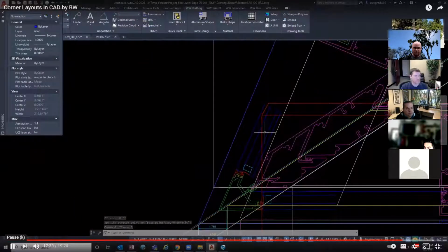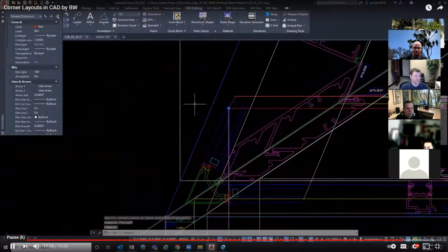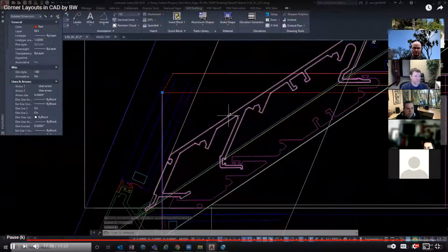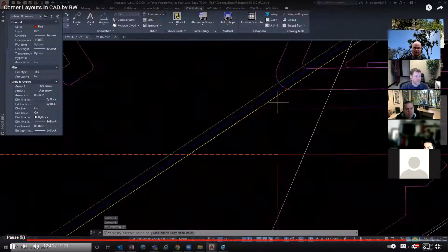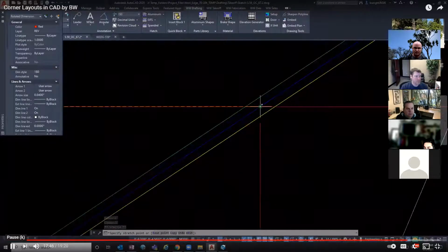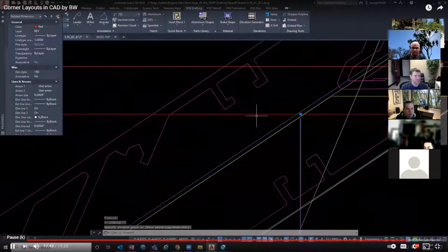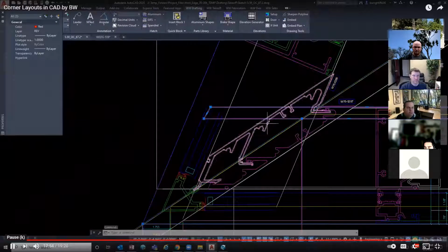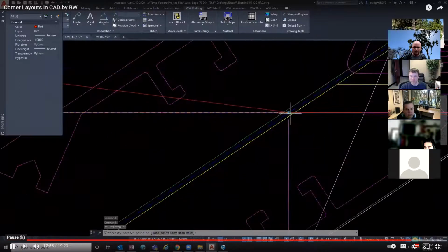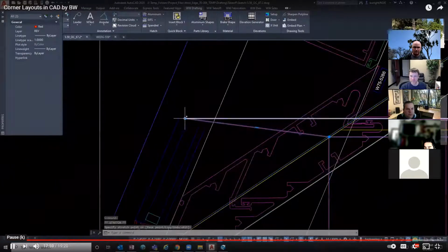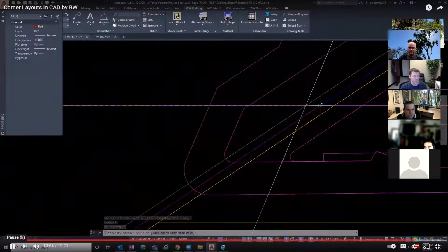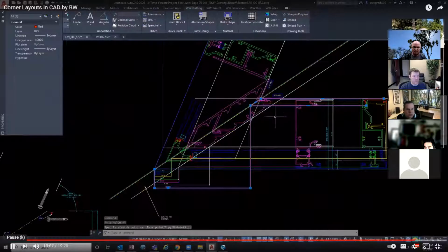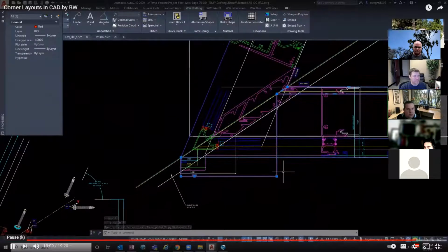And my final polyline is going to be the drive-on stop on the back. This one is also offset 1/32 from the center line. So I'll move my dimension over to the intersection of my blue line here. Then my polyline, I'll move in the same way as I did the others. Bring that back to here. And here. So now my layout is complete.